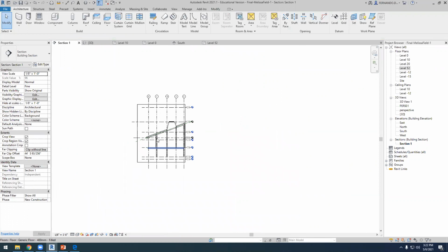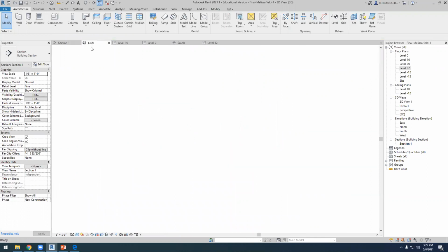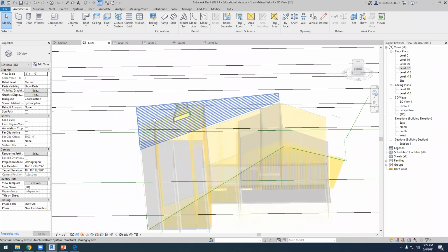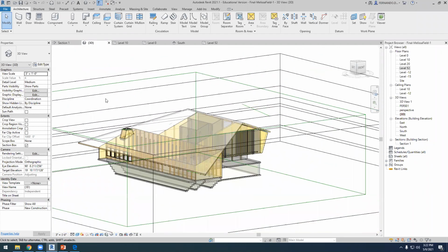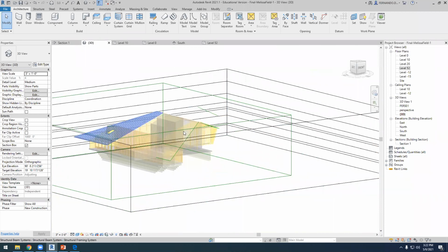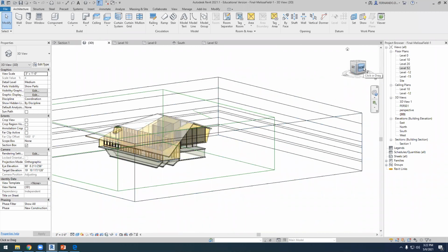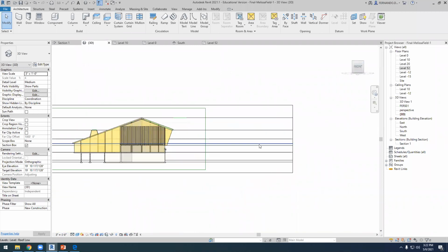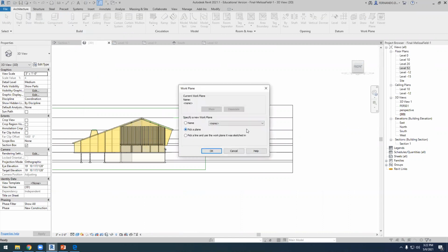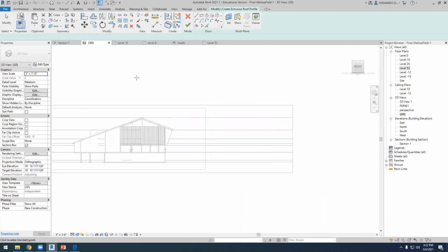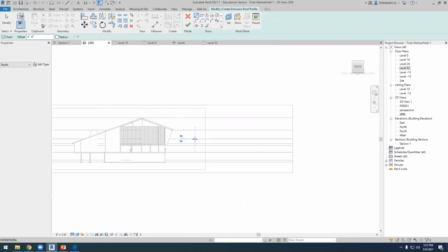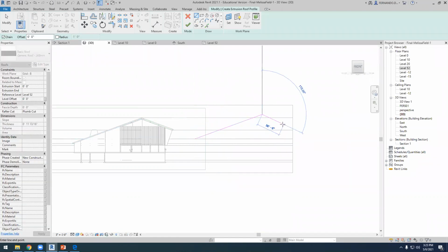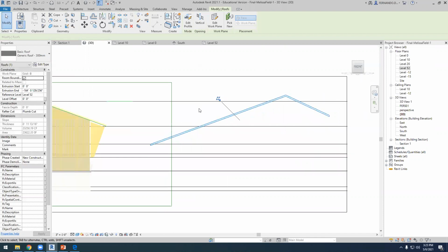What if you have created this roof using a roof by extrusion? Okay, so that's the other option to work with this. I'm going to show you. Imagine that you are using Architecture, roof by extrusion. We are in grid B. And using roof by extrusion, we can do the same shape that we have here. And then we click OK, and we do have the roof here.